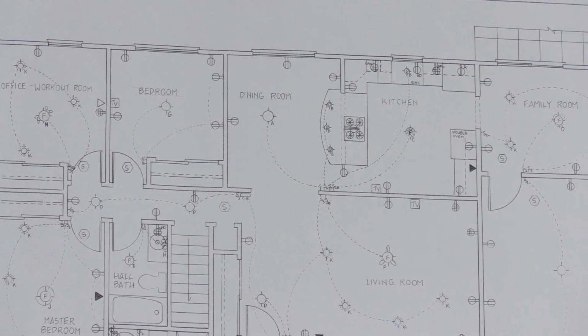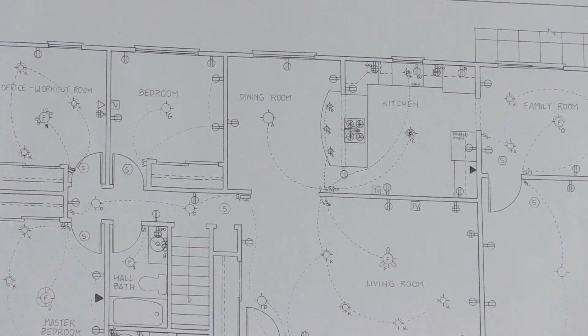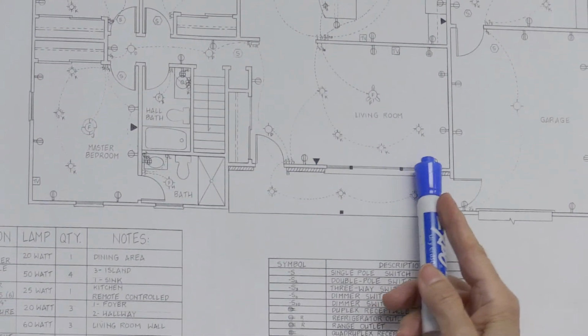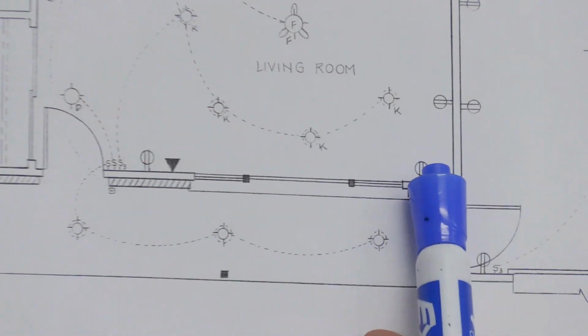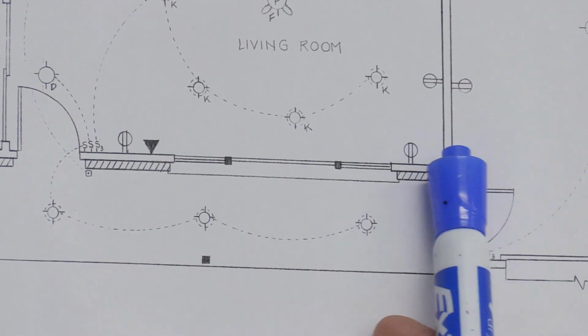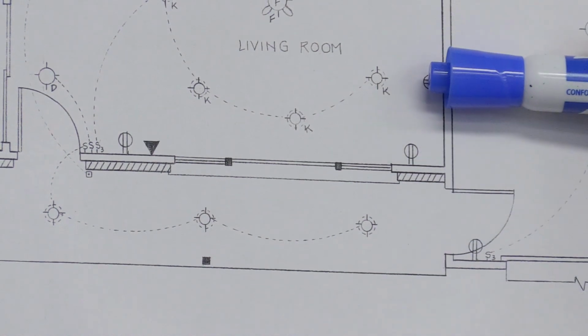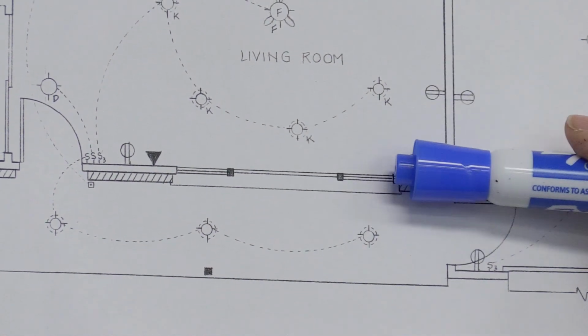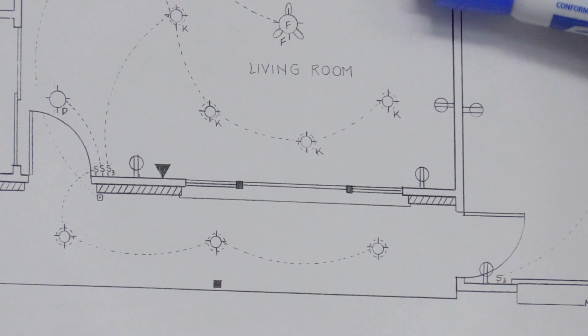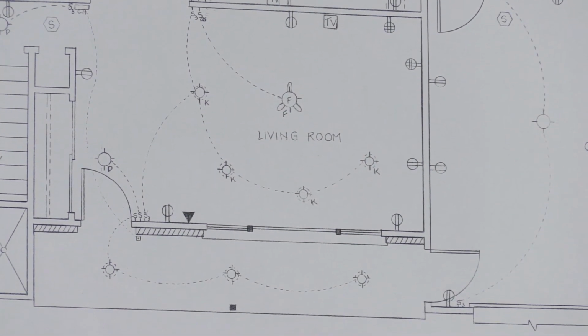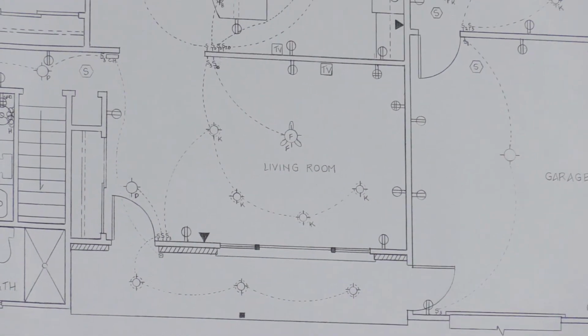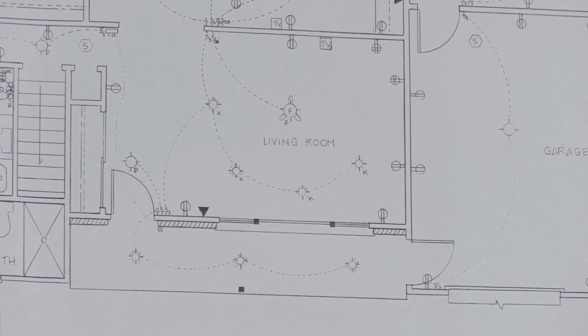And the 12 feet is that you cannot go more than 12 feet apart. That's the maximum that you can go from outlet to outlet. So you can be less than 6 feet from the wall, but the maximum you can go is 6 feet, and between two outlets, the maximum you can go is 12. You can go less, but you can't go more than 12.